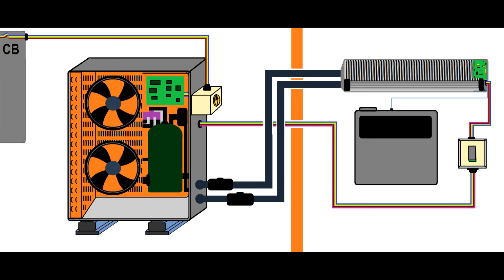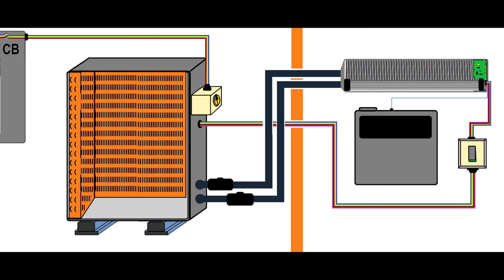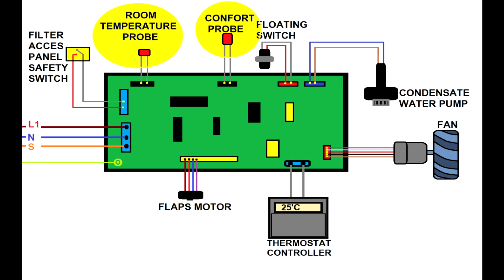You'll get access to the condenser fan motors. You'll see partially the condenser. If you remove the compressor and the printed circuit board, you will see more of the condenser behind. And finally, if you remove the fans, you'll have access to the condenser. This is a hard job and I really hate it.